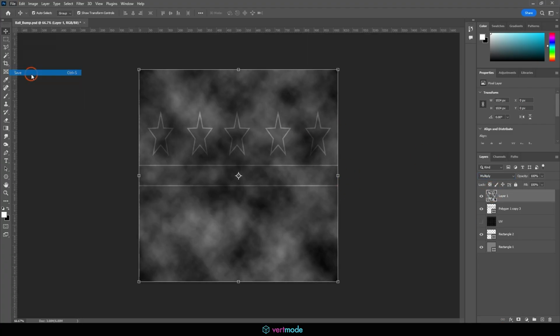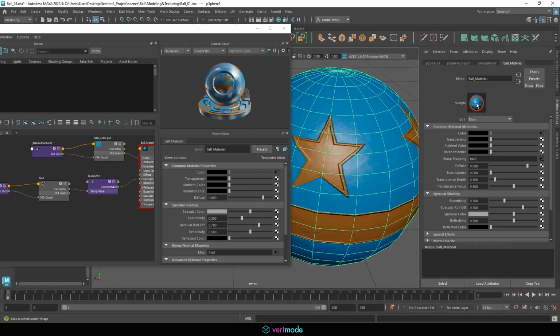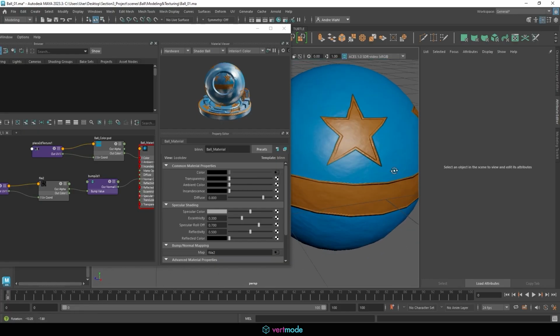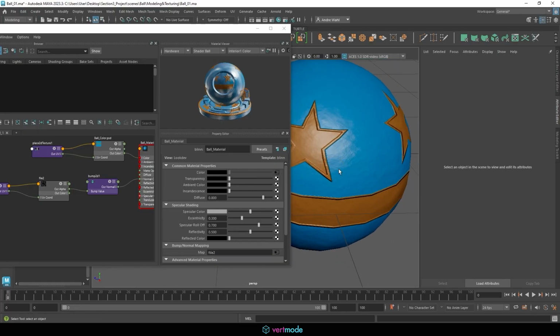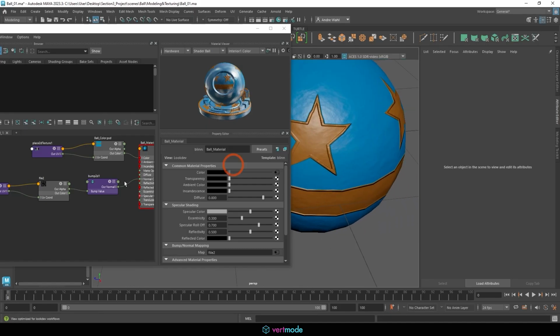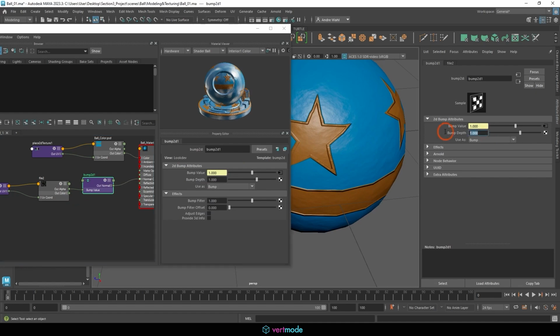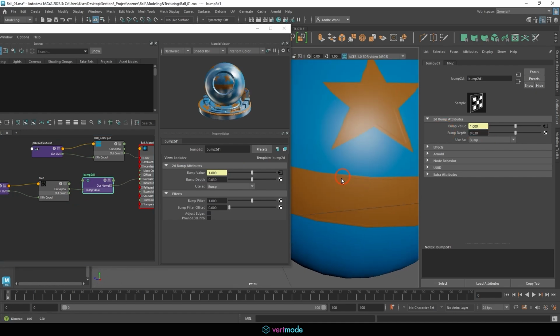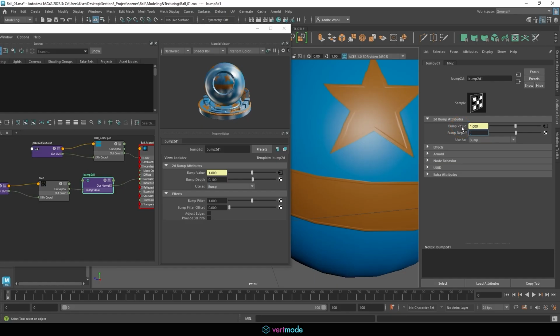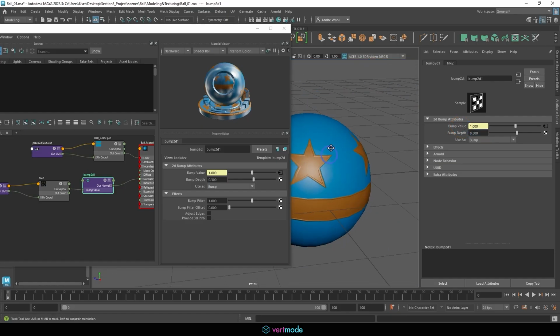We can save and we can see the result here. And double click. And you'll see now we have a little bit of a surface texture and those look pushed outward a little bit. So we're getting the best of both worlds. Now it's a little bit intense across the board. I could come to the bump 2D here and set this to 0.03 to see the result it gives me. And in this particular instance, we're getting a little bit too subtle, maybe 0.1, maybe 0.3. So maybe somewhere around there.